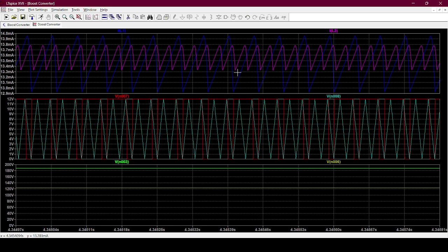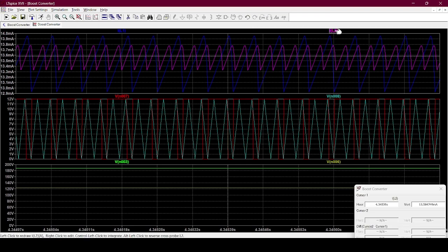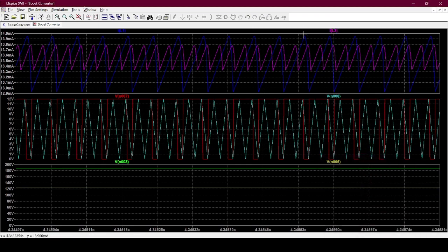They are not sinusoidal. They are not even close to sinusoidal. They are not behaving in two directions, as you can see. They are fluctuating between two points or two rough values. They are behaving like a saw, like some sort of a triangular wave. So the RMS of this current, you can see it. The RMS of this current is not like sinusoidal. You cannot calculate this RMS by taking I maximum over root 2. It is not even logical.